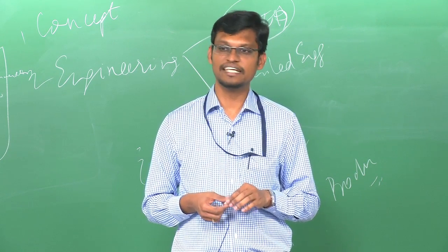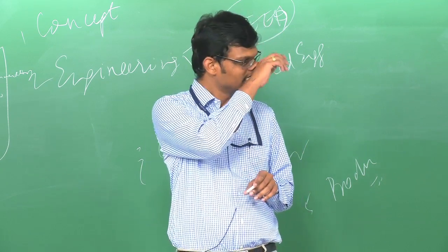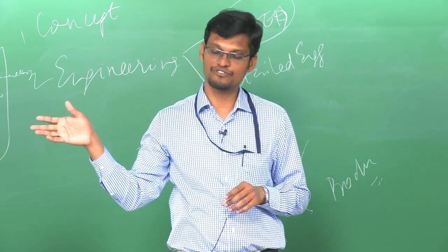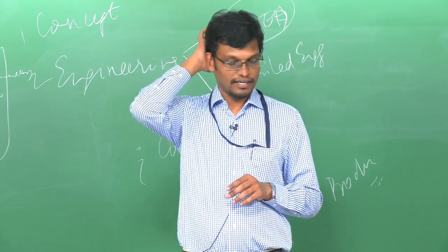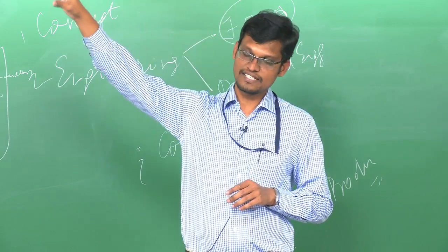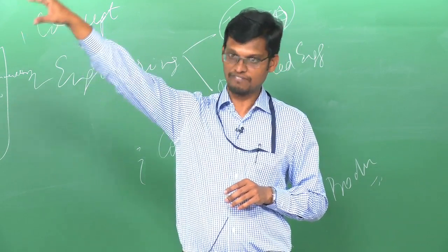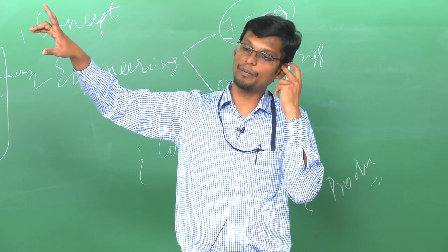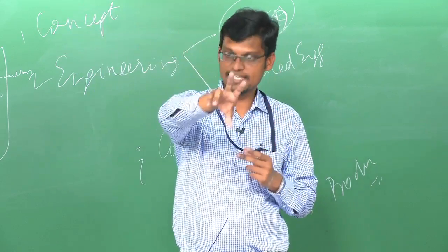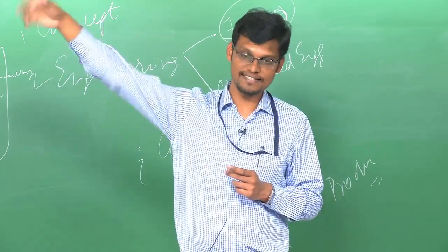Have you guys seen a HAZOP report any time? No. Okay, fine. I will just give a simple example. Maybe subsequently in the next few classes you will try to understand it in a detailed way. For example, a control valve is there at 3 meters elevation, and you expect an operator, assuming he sees a parameter, to go and operate that valve. Will he be able to access it safely?